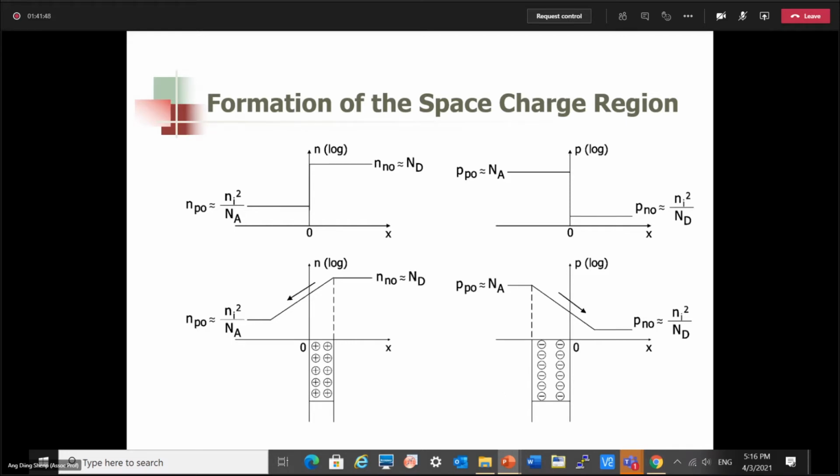Sorry, I have one more question. We are looking at the P region of the space charge region, right? Meaning the positive, the P side. So wouldn't the boundary condition be more apt if we use the boundary between the positive space charge region and the negatively doped region? Since you're assuming that this density is approximately negative qN_A.